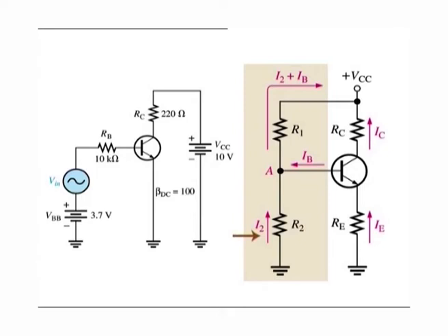In this case, the voltage divider circuit is very straightforward to analyze because the loading effect of the base current can be ignored. A voltage divider in which the base current is small compared to the current in R2 is said to be a stiff voltage divider because the base voltage is relatively independent of different transistors and temperature effects.